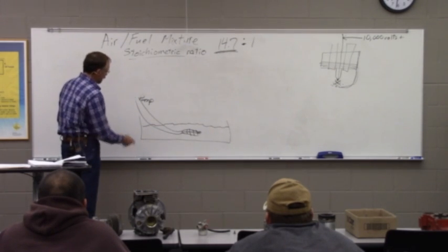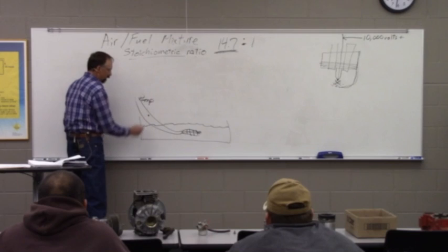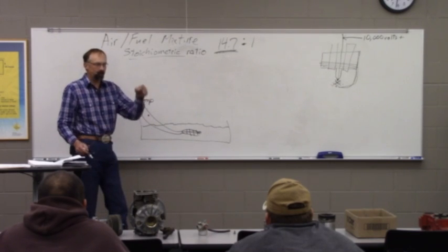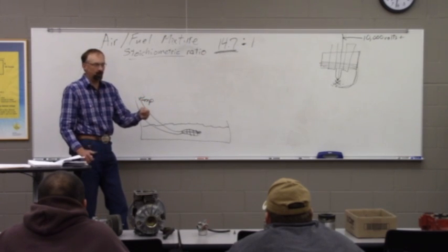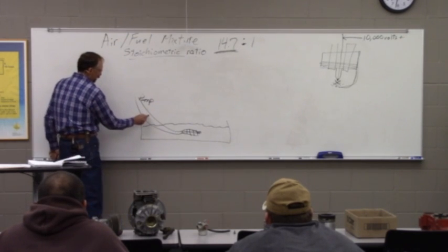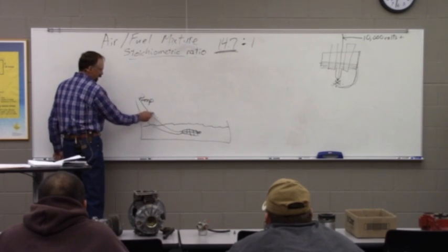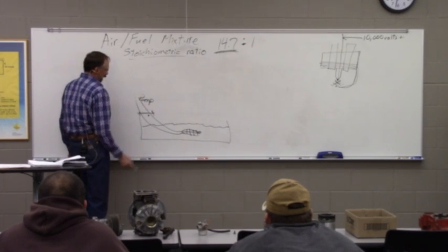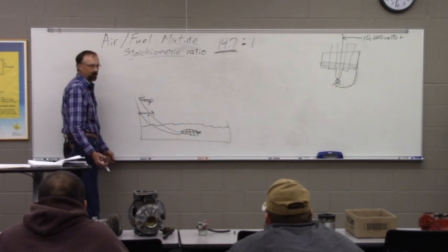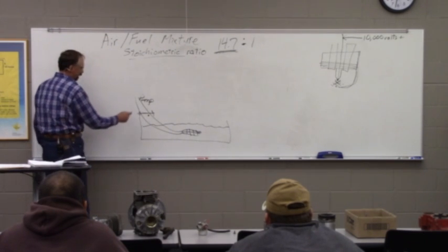There were a few engines that had troubles with this. If you can imagine, if there's a pinhole right here, same deal as if we took our drinking straw and poked a hole in it, what comes out of the top? All liquid or air? So if you either have a crack in this pipe or a rust hole in this pipe, or there's a joint in it with a gasket and the bolts have come loose, it's going to suck air. If it sucks air, you got a bunch of air bubbles in the oil, the parts aren't getting lubricated like they should, and there's going to be some failure there.